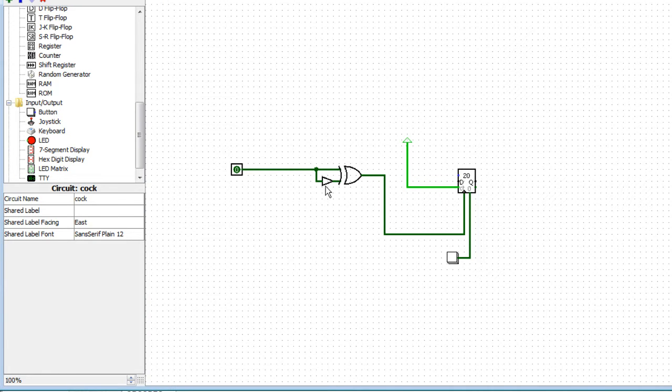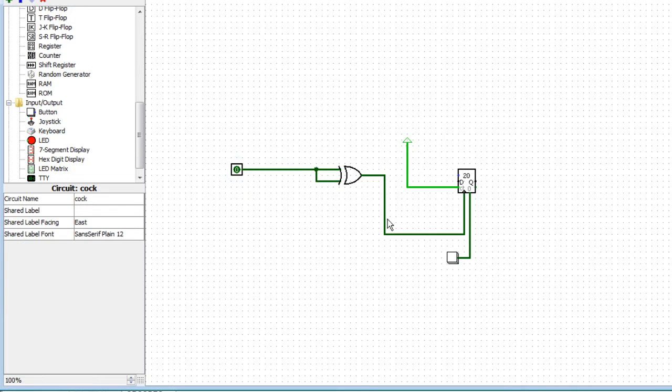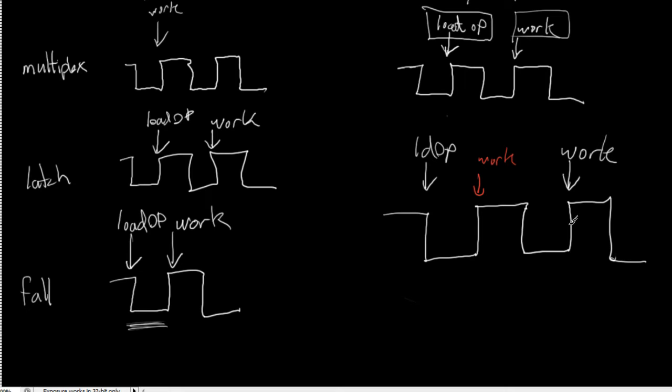Basically, and it doesn't work if you take this buffer out, by the way. You get nothing. You lose, sir. So why does that work? Basically, if we take a look at the timing diagram of this circuit here, we can see what's going on. Yes, the buffer is a delay. That's the only thing it does. It is a gate, and so in the simulation, it has a one-step delay.